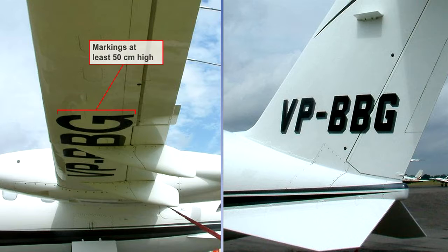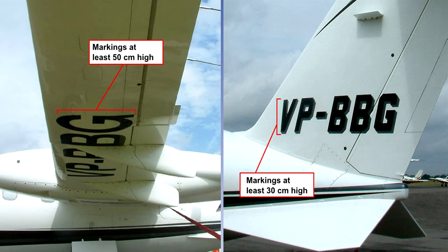The markings on the wings are to be at least 50 centimetres high, and on the fuselage and vertical surfaces, 30 centimetres high. This completes the lesson on aircraft registration markings. You should now understand why aircraft need to be registered, how aircraft are registered and what the registration mark means, which registration marks are not suitable, and where the registration mark is to be displayed on aircraft.